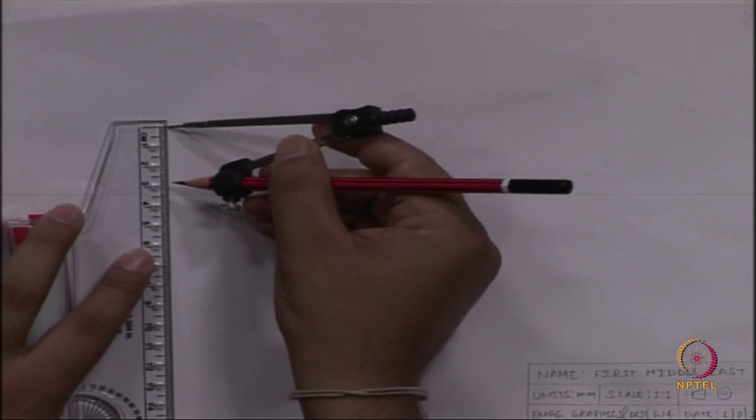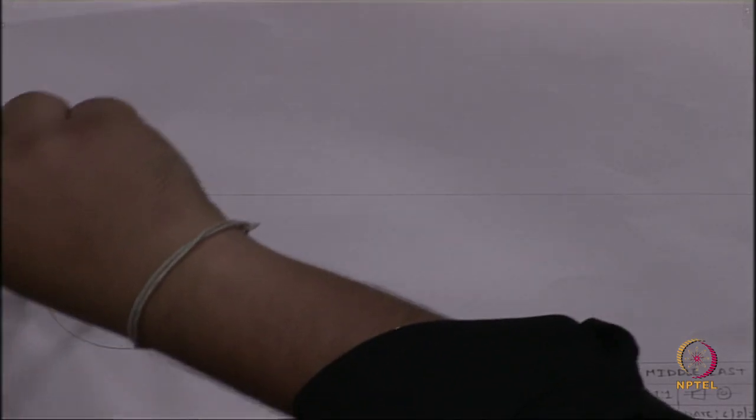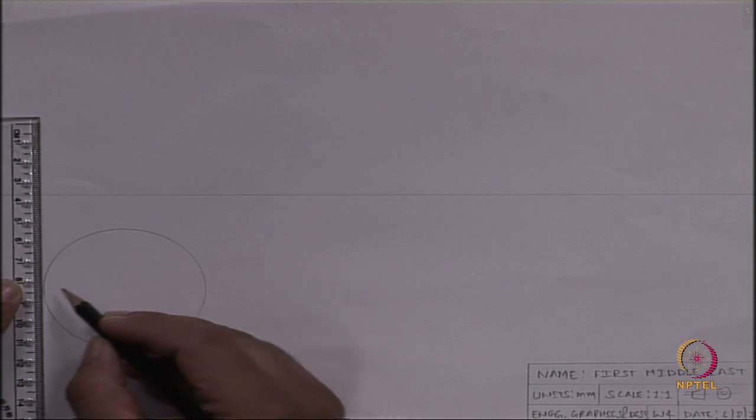We have the reference line. Now, taking an arc of 30 mm and drawing a circle having 60 mm diameter, we can take random point below the reference line, since the distance between the apex or any of the point on the cone from the vertical axis is not given. This is our top view. Now, for front view we will use the projection lines.